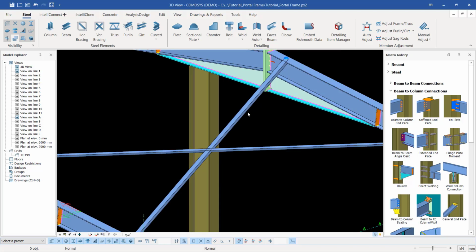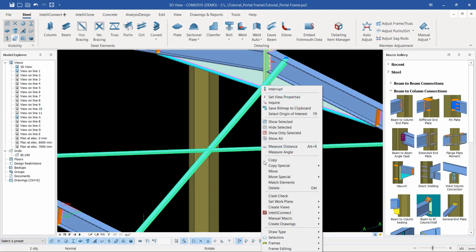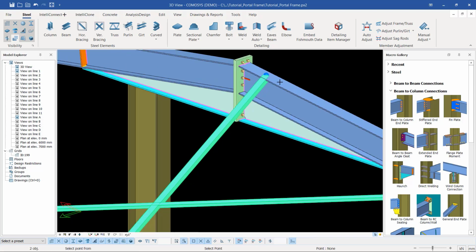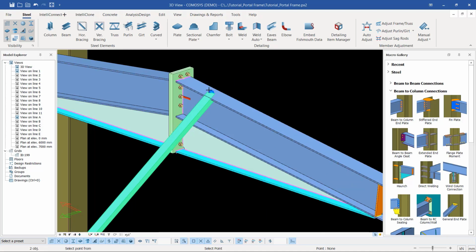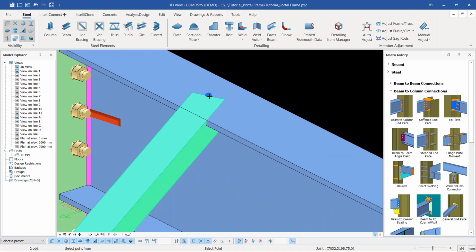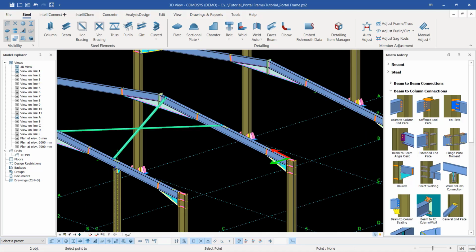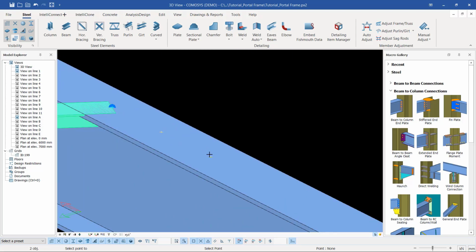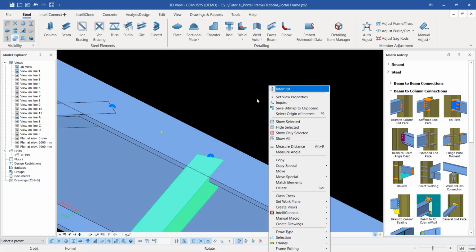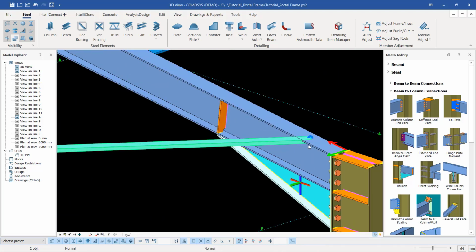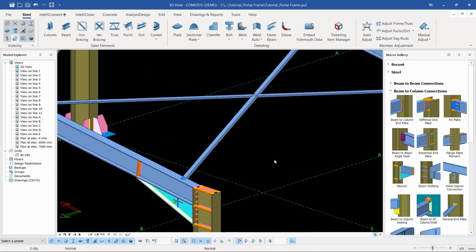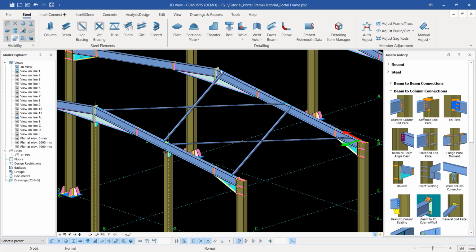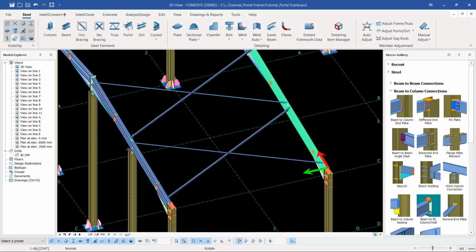So once you've done so, just select this member, right click and come to copy, and move this member from this particular spot here where we placed our point, and come and place it here. We've just copied that into that location. So you can see we have another point there, we have another point here. So that's how you can brace that. So let me just select on that member and try to rotate.